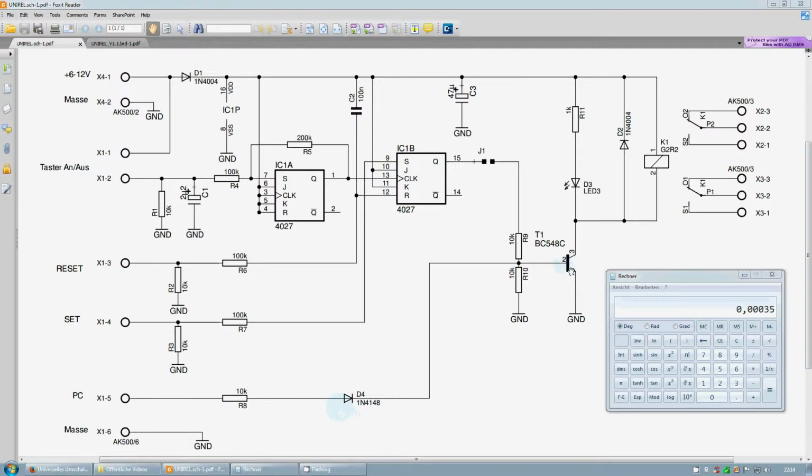Well, about half a volt or 0.6 volt is lost in the base emitter junction. Another half volt is lost here, and the voltage that must be across R8 is simply these 350 microamps times the value of the resistor according to Ohm's law, and this is 10K. So we multiply by 10 kilo ohms and we get 3.5 volts.